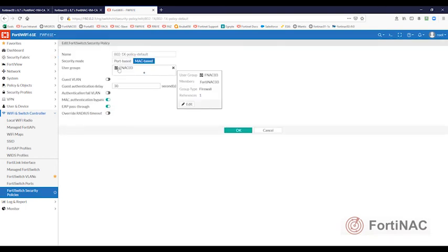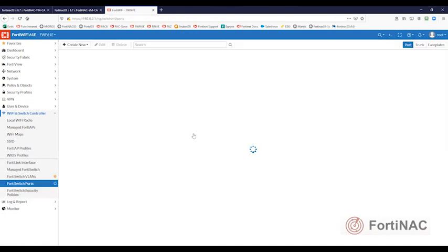Basically, I'm using FortiNAC as the RADIUS server because FortiNAC knows the MAC address of the PLC device, and will appropriately answer that RADIUS request coming in, and we're doing MAC authentication bypass. So I have FortiNAC set up as the RADIUS server. I'm sending the MAC address over as soon as it connects into the switch port, and then I'm seeing on the port the device will show up in the appropriate network.